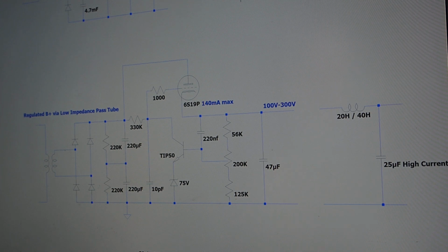However, I would always upgrade the components to long life and low ESR capacitors, and I would use better diodes than what you get standard. And yeah, I really can recommend using a very low plate resistance tube; that generally works best. I think that is essential for getting the most out of this circuit.